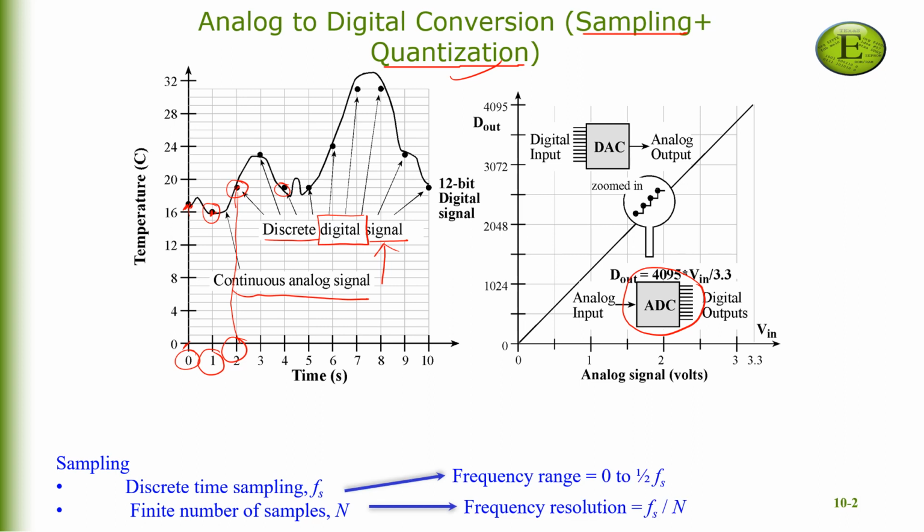Before proceeding, it is important to note that once the signal has been sampled at the sampling frequency fs, the highest frequency component that can be recovered from the analog signal is half of the sampling frequency. We should also note that in real life applications, we can only record a finite number of samples of a signal, even though theoretically the signal duration is infinite.